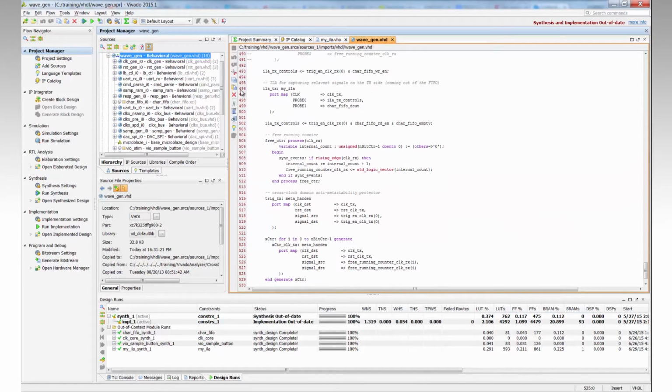When you instantiate the ILA, you would want to connect the probes to signals that are all within the same clock domain. You also connect the clock signal of that clock domain to the IP. Once this is done, you can proceed to synthesis and implementation of your design. Remember that these steps for the instantiation flow are the same for adding any Logic Debug IP to a design.